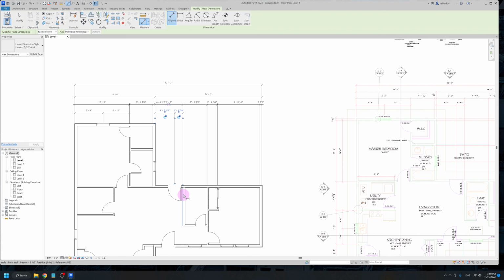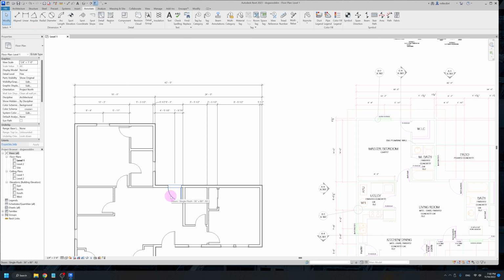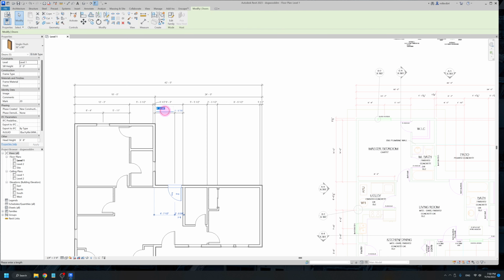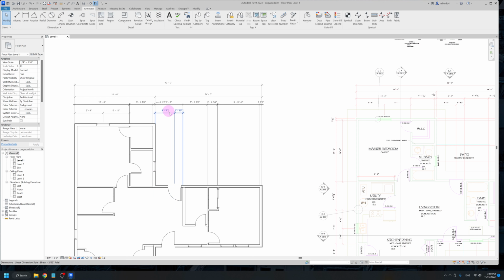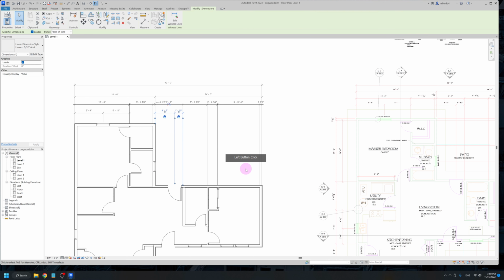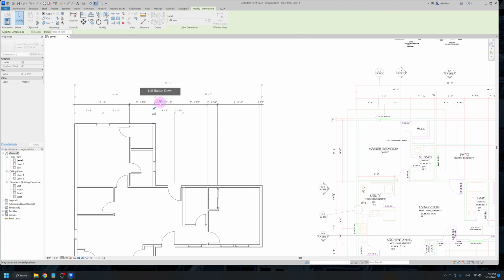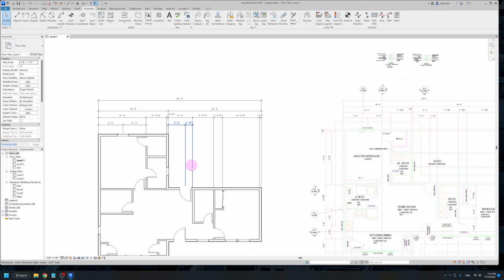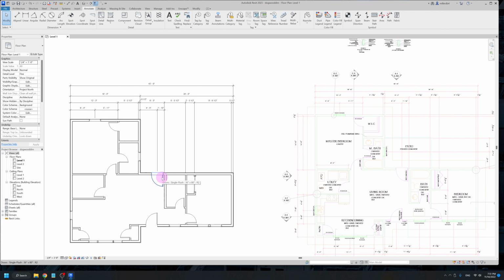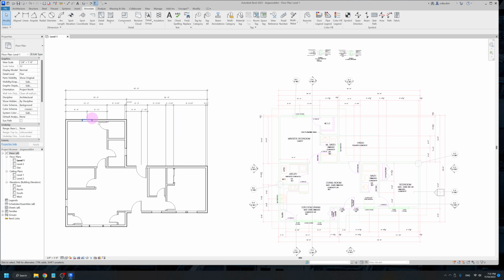And then I want to move the door over, in my case, just 1/8. So I'll hit escape twice. I'll click on this door and I'll do 4'5", enter. And now that door is moved over. It didn't even look like it moved over a little bit, but I just want to make sure that I'm using measurements that are going to be pretty friendly for my contractor, so they're not getting there and having to measure something to be 1/8 of an inch of a difference and things like that. And so at that point, I would have all of these numbers going across the north side of my building ready to go, and they match the dimensions that I was given from the CAD plan.